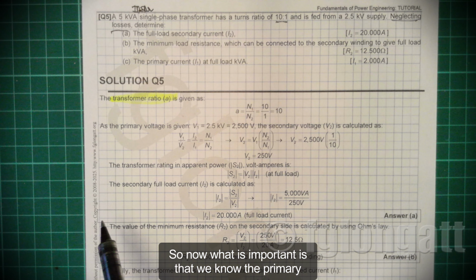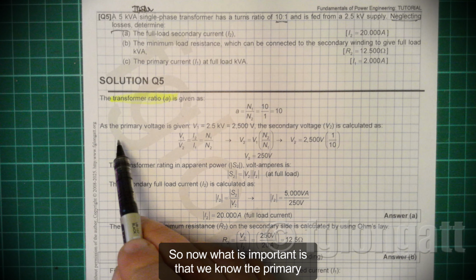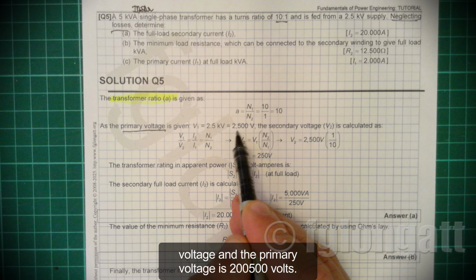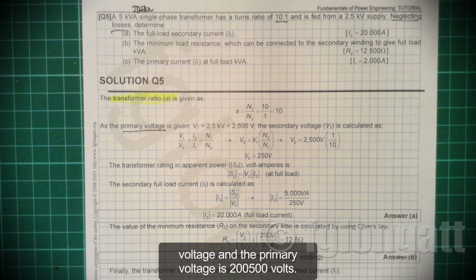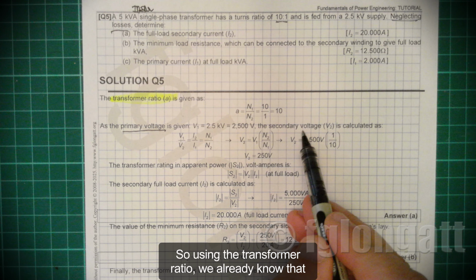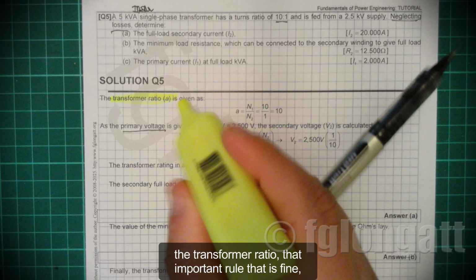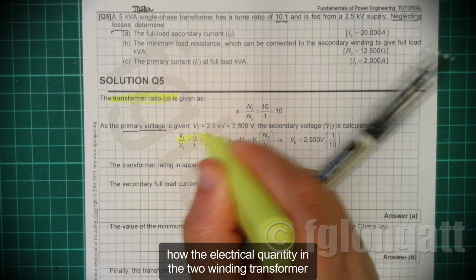Now what is important is that we know the primary voltage, and the primary voltage is 2500 volts. Using the transformer ratio, that important rule that defines how the electrical quantities in the two-winding transformer are modified, we can calculate the secondary voltage.